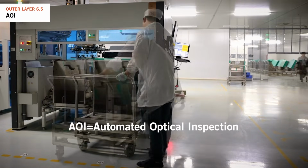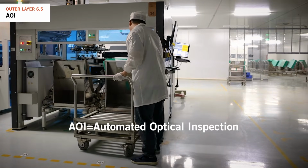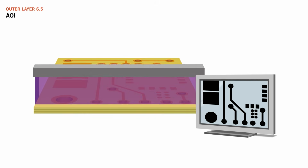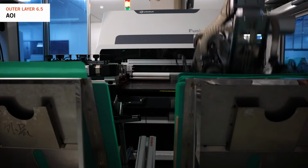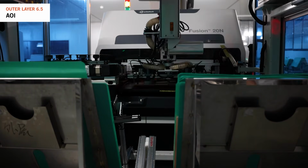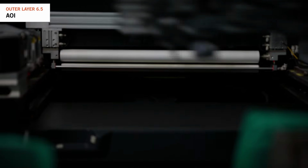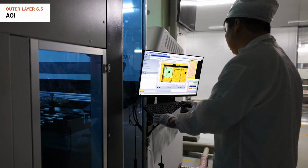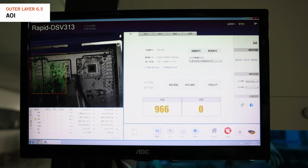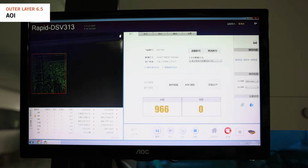Automated optical inspection is a way to scan the copper circuitry on outer layers and compare it to the design and the Gerber data to verify that the pattern defined is correct. Before scanning with AOI, we clean the outer layers to remove any debris or surface contaminants. Then the machine does the scanning, comparing the scanned image to the customer's Gerber data. The AOI scanning identifies any concerns, such as errors or faults with the pattern, thus preventing the use of faulty outer layers in the production of the circuit board moving forward.